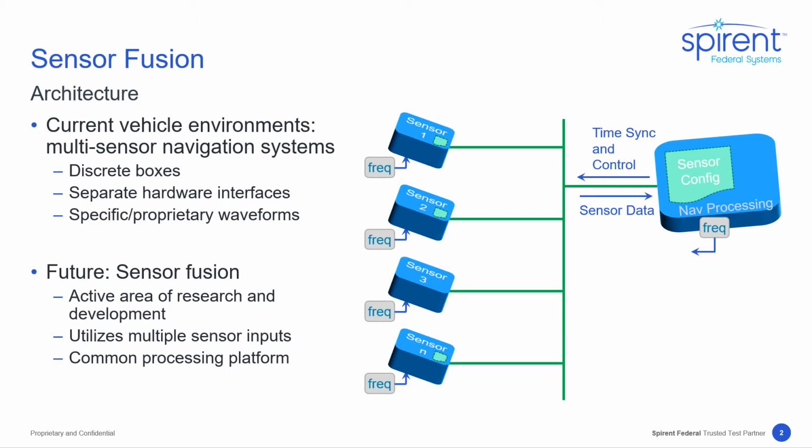The key implication of this architecture is that despite the architecture change, as always in navigation systems, timing is key. To maintain timing and synchronization, high-quality frequency references and time synchronization messages are employed. In real sensors, this keeps time and rate outputs from drifting. In simulation, one of the boxes on the left is a simulator, outputting multiple types. Errors are also simulated, so having the time and frequency references allows for modeling the actual sensor effects. If following open source standards, as we will discuss in a bit, as long as the device adheres to the standard, sensors are interchangeable.